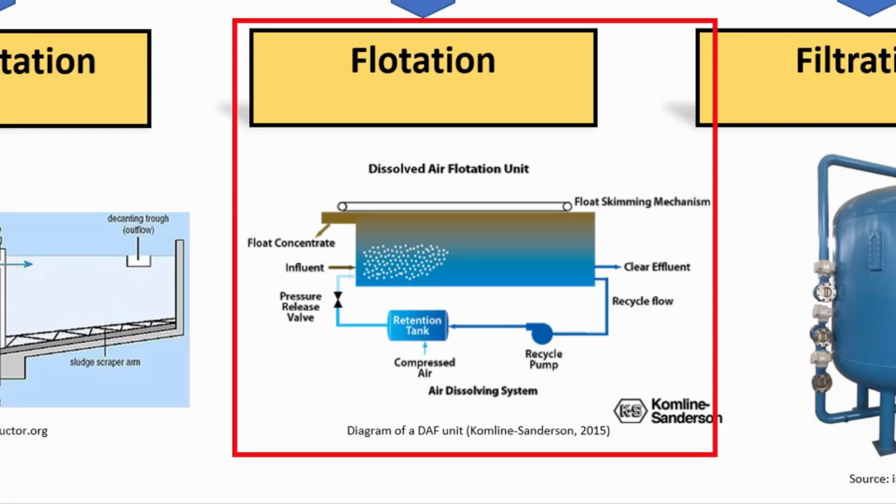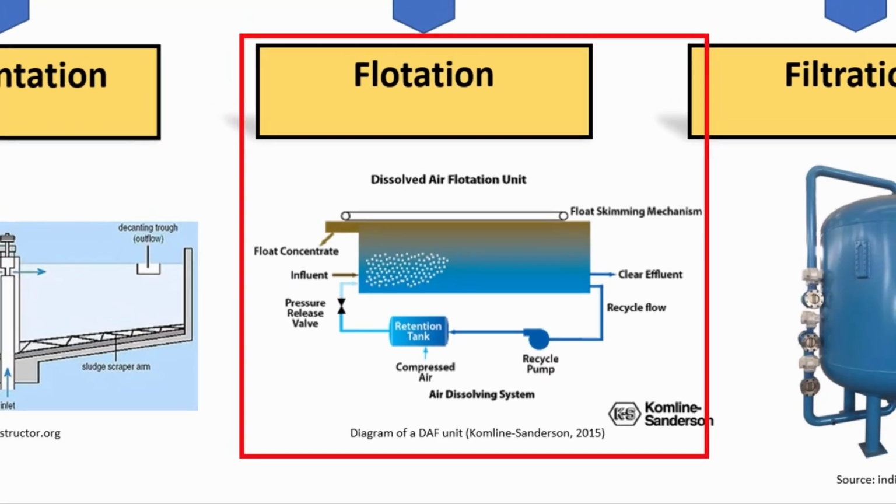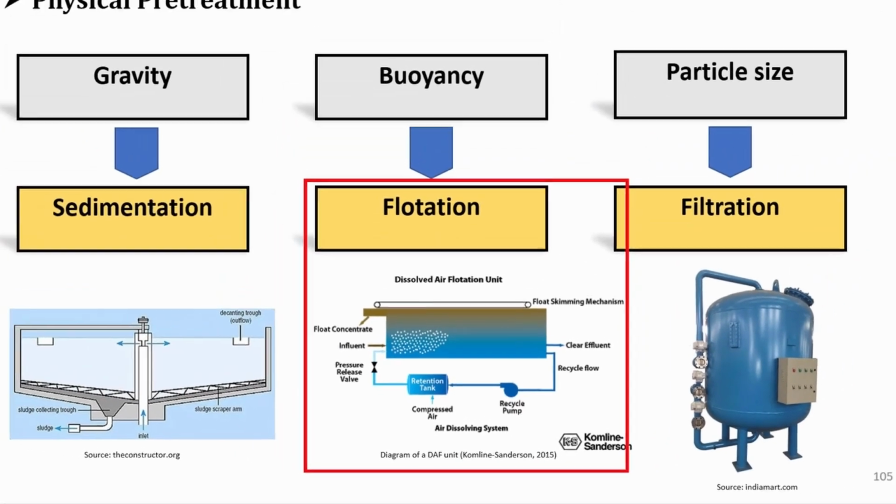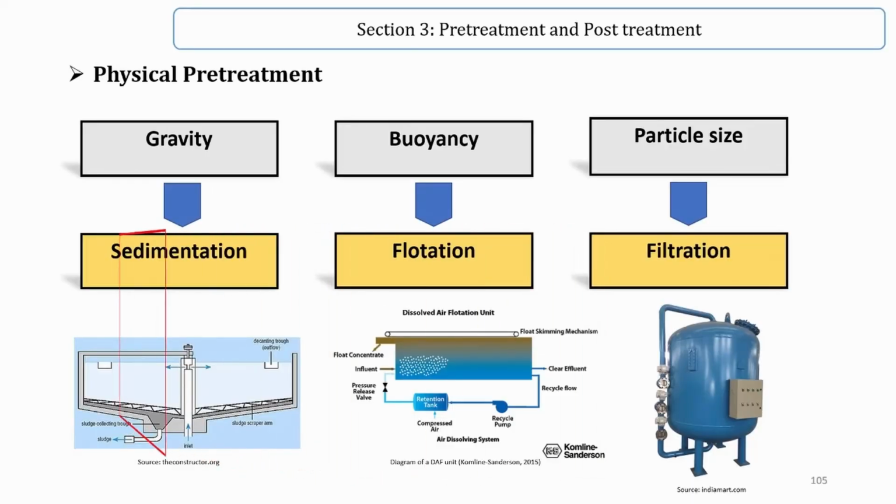In water treatment, the most commonly used method is dissolved air flotation, or DAF. In this process, a partial flow of the treated water is saturated with air under pressure. The air-saturated water is then passed back to the inlet region of the flotation tank as circulation. An expansion valve is located just before the inlet to the flotation tank, which causes the water to suddenly re-expand to atmospheric pressure. This expansion causes the dissolved air to form fine bubbles.